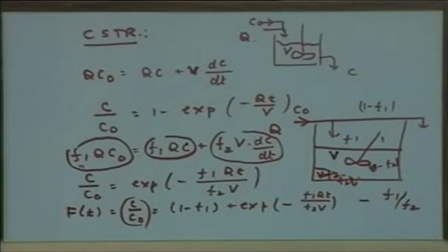That just illustrates that the use of residence time distribution in the case of a real reactor can be used to determine the reactor performance, and such performance can then be used to calculate or correct the actual performance based on the kinetic data.